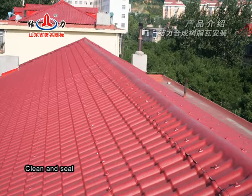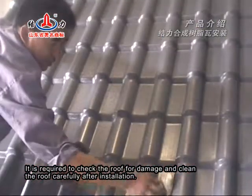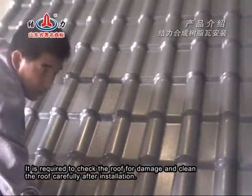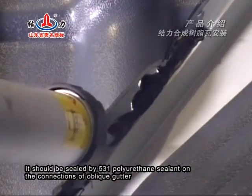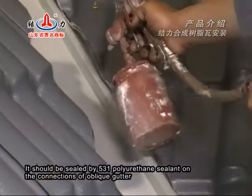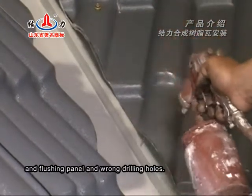Clean and seal. It is required to check the roof for damage and clean the roof carefully after installation. It should be sealed by 531 polyurethane sealant on the connections of the oblique gutter and flushing panel and wrong drilling holes.